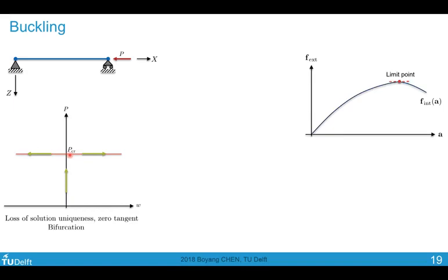Now, putting it into context of our nonlinear analysis, I'm sure you're already familiar with this plot. Previously, the tangent stiffness becomes 0 when we have a limit point. Now, I've also mentioned that there is a 0 tangent at the point of bifurcation, which means that in a higher dimension situation, we could reach a state of loading such that our tangent stiffness becomes singular along a certain direction before reaching the limit point. And our solution could then take a secondary path, which is orthogonal to our original path. Physically, this means that our new displacement is orthogonal to our original displacement solution.